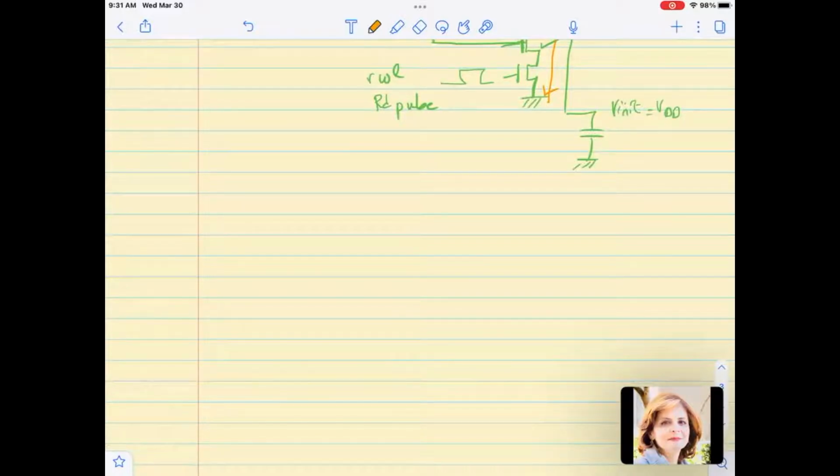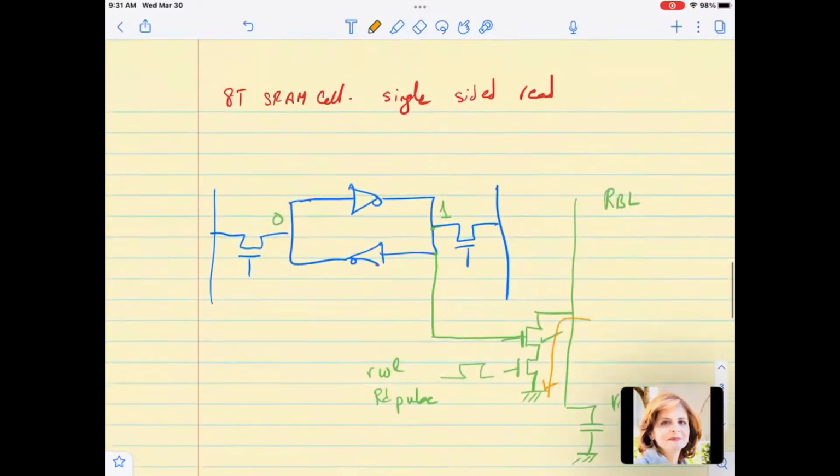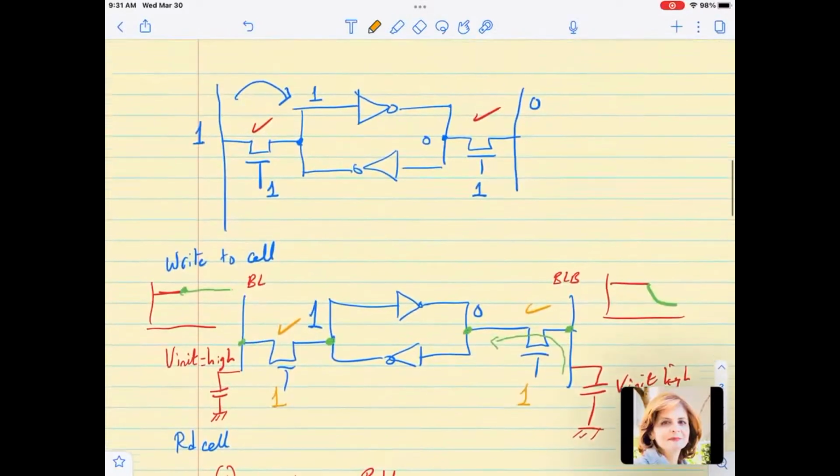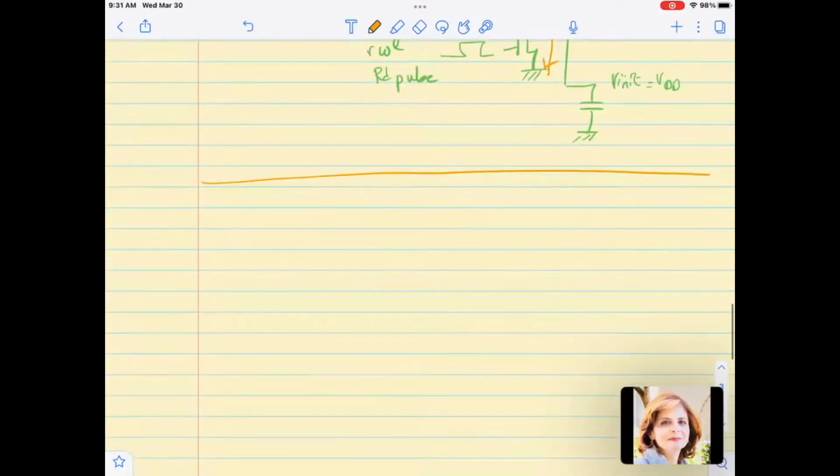Now other types of volatile memory are dynamic random access memory. So this is static random access memory, the SRAM, because once we write the value we don't need to refresh it. The dynamic random access memory is one transistor with a big capacitor. Okay, and basically it is not like this, pardon. And basically this single transistor is used to write, meaning to charge or discharge the capacitor.